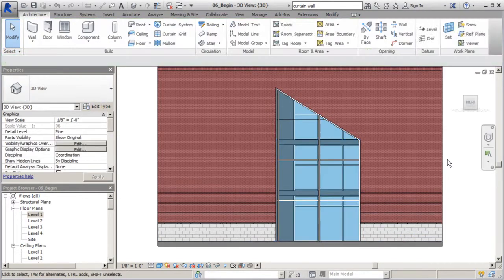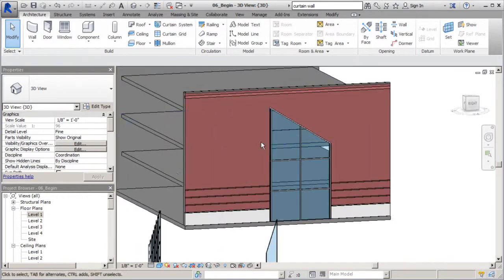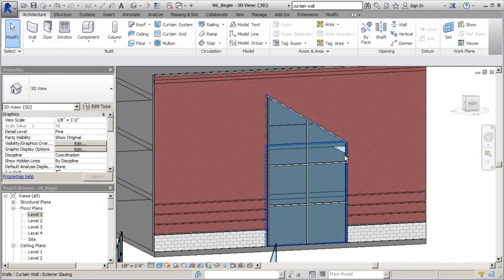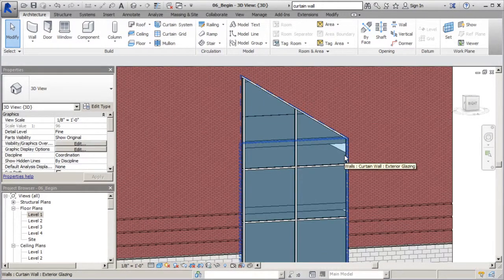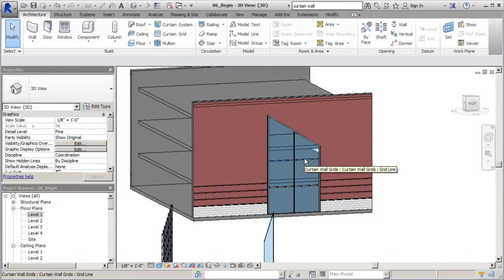Now you'll notice something, just like with the storefront system, it's the same thing. When you hover over the wall we just adjusted, you'll notice that rectangle is still there by the dashed lines that are really close together. You could see the original form right here. But although that's in place, it still models out the change we made. So that comes in handy. So you can definitely still edit the profile even when you're working with that one.